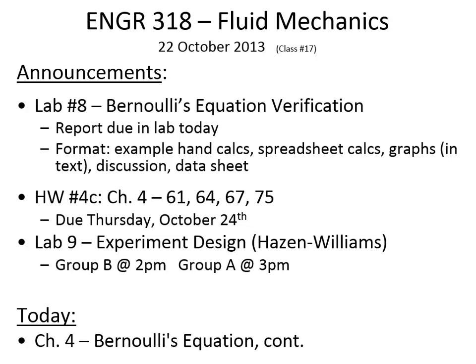And the energy grade line, EGL, being above that is sort of telling you that the pressure went into the velocity head. That there is a little bit of a loss. There will be a downward trend because there is energy loss through that venturi meter, but there's not a lot. So the EGL line hopefully should be relatively flat.